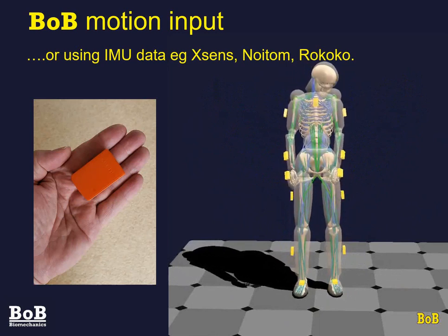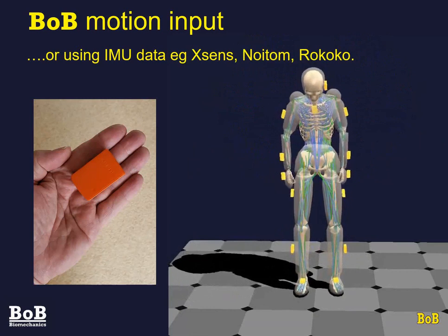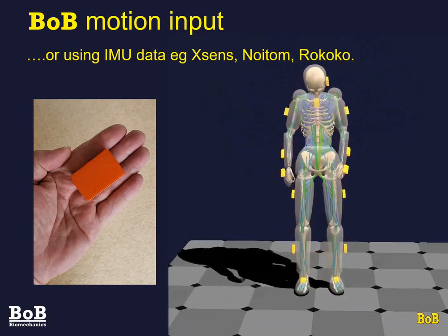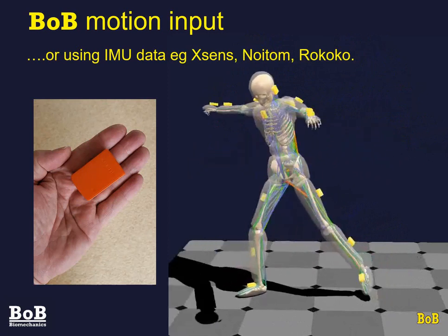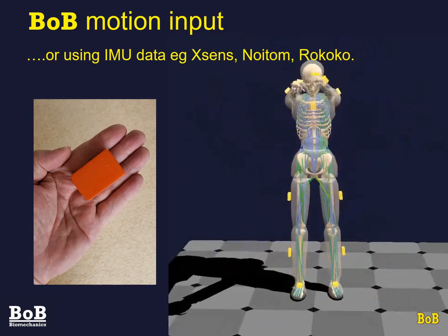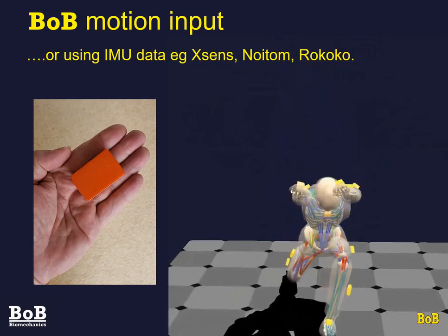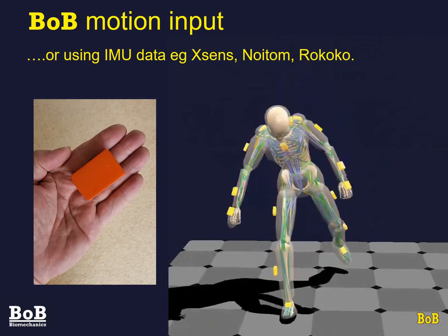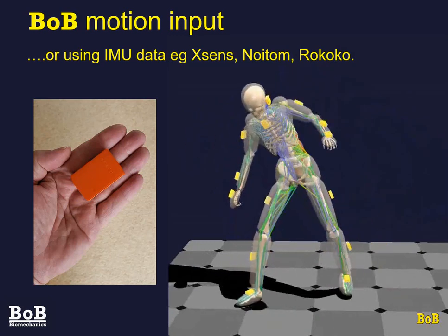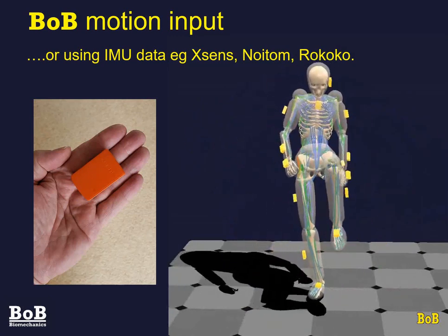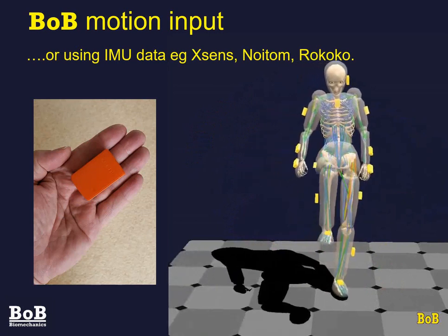However, this approach can be susceptible to drift because the motion tracking requires the double integration of the acceleration data to calculate the positional data. But a consideration of the ground contact and the magnetometers can normally be used to remove this drift completely. Some IMUs can be disturbed by the presence of ferric objects. However, recent developments have virtually eliminated this issue.